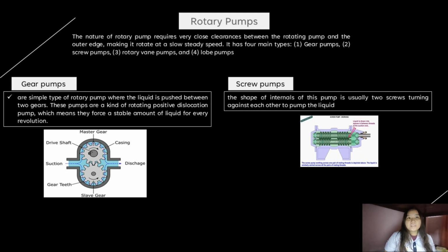For the screw pumps, these types of pumps operate using counter-rotating screw rotors, which are engineered so that they rotate towards each other. This traps the gas in the space between the screws of their rotors. As the screws rotate, this trapped volume decreases, which not only compresses the gas, but moves it towards the exhaust.